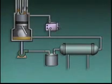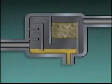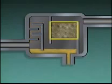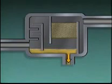Most reciprocating compressors that contain pistons use oil to lubricate the piston rings. During compression, some of the oil can become mixed in with the gas. This oil must be removed from the gas to prevent system equipment from being damaged. Oil removal is accomplished using oil separators. This illustration of an oil separator includes an inlet, a series of baffle plates, a wire mesh screen, a sump, and a gas outlet.